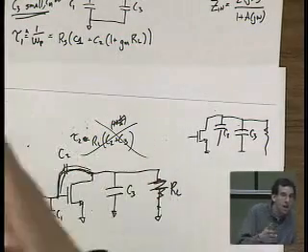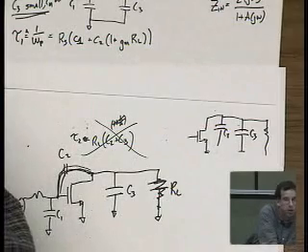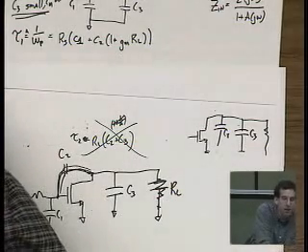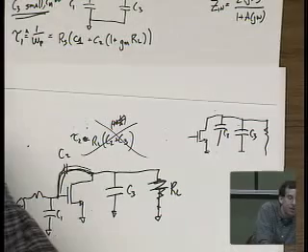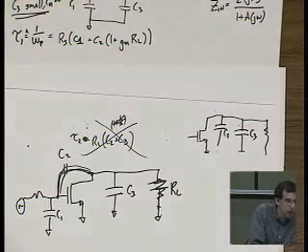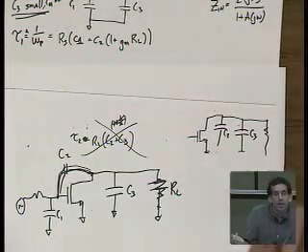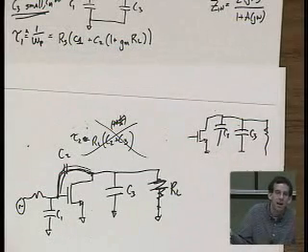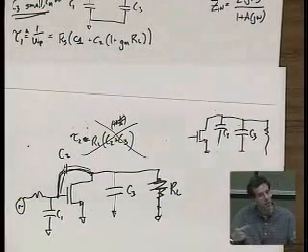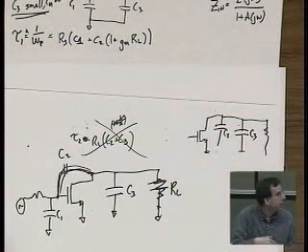So it starts acting at a very low frequency, right? When capacitors start acting and start limiting the bandwidth, what they're basically doing is providing low impedance paths, right? And when they provide low impedance paths, that's what kills the gain. But if they provide low impedance paths, that also means that you can talk both ways through them. So stuff that goes on at the output is translated back to the input.